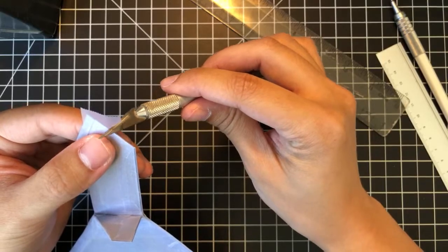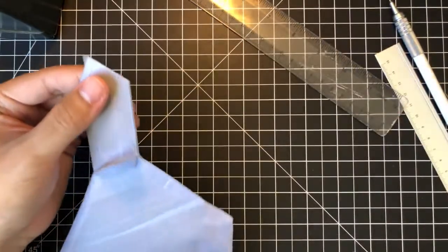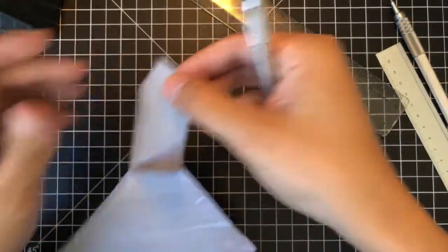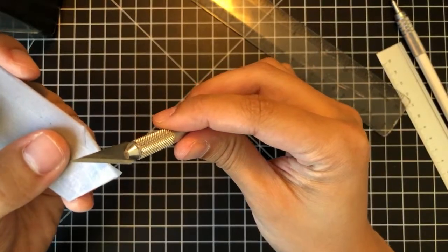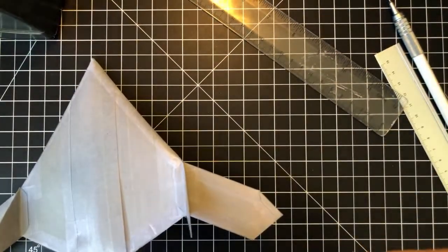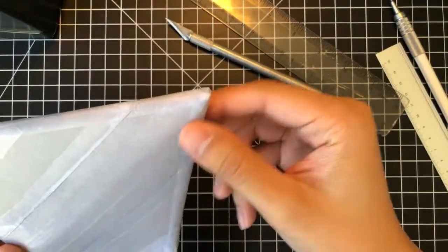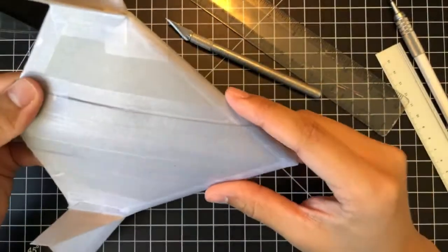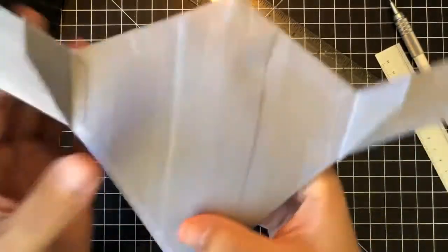But since I haven't done any lamination in a while, it's just kind of escaped my mind. Really should do it that way, from the trailing edge forward. And again, it's a small detail, but it will affect your drag characteristics. Right, if it's stepped against the airflow, you're gonna have more drag, more skin friction.